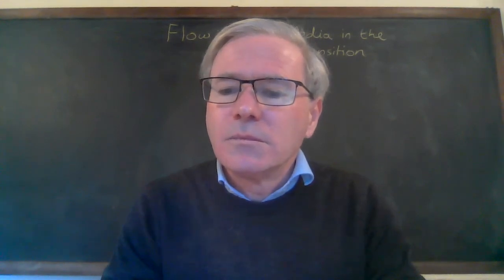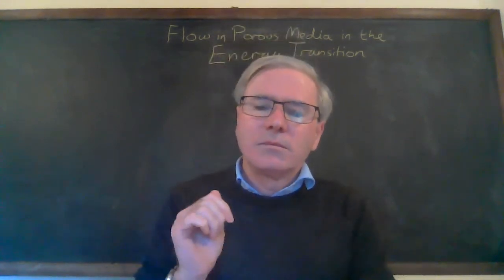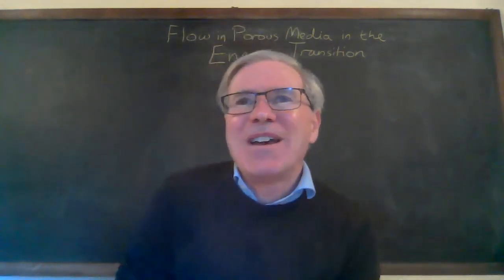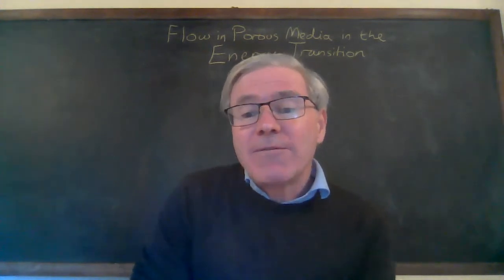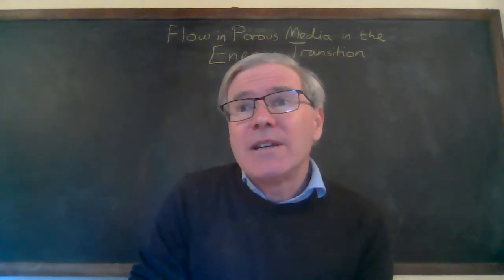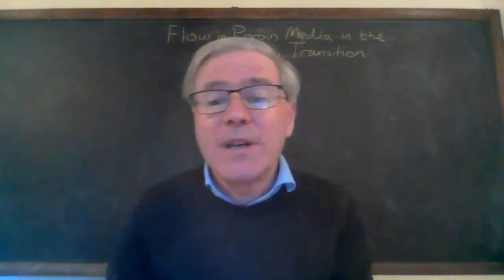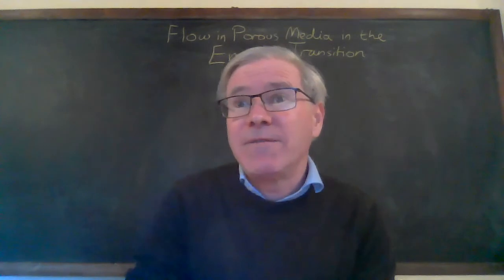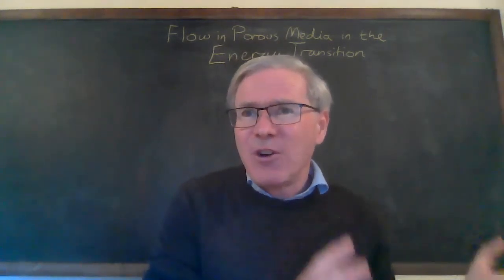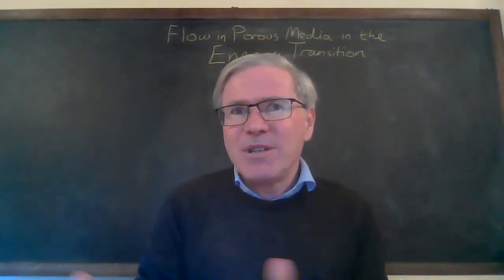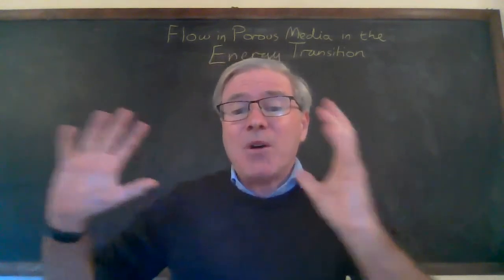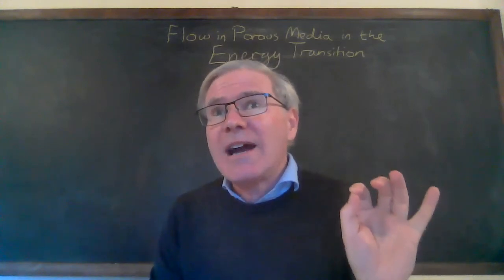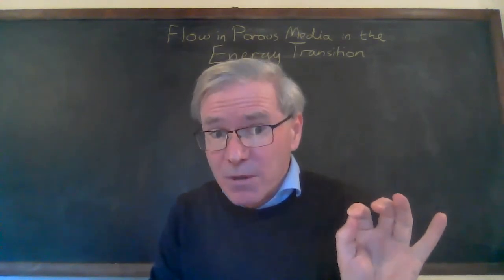So one basic question: what is the difference between flow and transport in porous media? Okay, good question. Yeah, I'm a little bit loose with my wording, certainly in a talk. So flow is, technically, just the volume of fluid flowing. So you have, for instance, the Darcy flux or the Darcy flow from Darcy's law, which is the volume of fluid that flows per unit area per unit time. So it's just a sort of bulk movement. Transport, technically, is actually how, say, an individual particle would move.